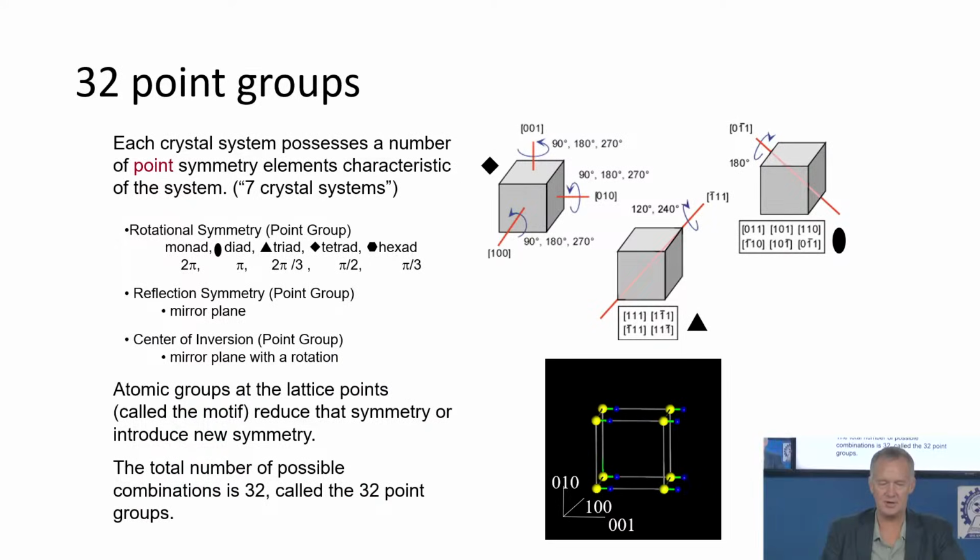All right, in crystallography, there's 32 point groups, right? So this depends on the centering. So we can have a cubic crystal symmetry, we can have it primitive, we can have it body-centered, or we can have it face-centered, right? And we can do the same with a lot of the other types of crystal systems, so you have to take care of those. Those different points are important as you're defining diffraction, and as you're defining the primitive unit cells that you can use to calculate the reciprocal lattice. Okay, because that requires only 1 point per primitive unit cell.